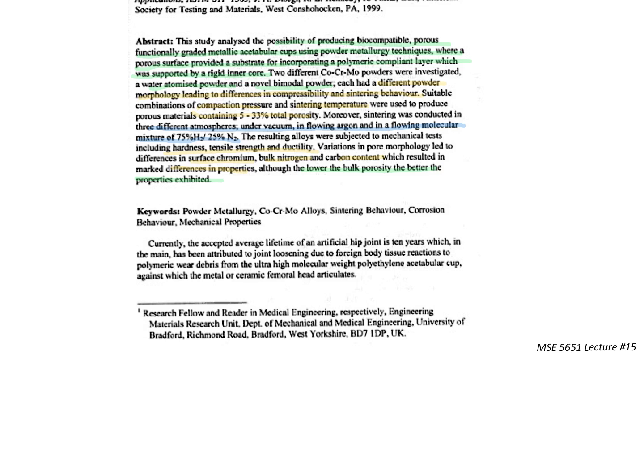So we know that hydrogen extracts carbon, right? And the higher the hydrogen content, the more carbon extraction this system will undergo. So if we raise the nitrogen and decrease the hydrogen, then we have less carbon extraction as a result. We absolutely need some to get rid of the oxide. The question is, how much do we need beyond getting rid of the oxide, and what does it do to the carbon content? Does that make sense?